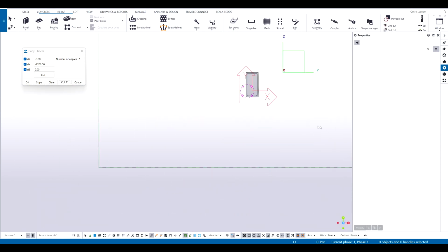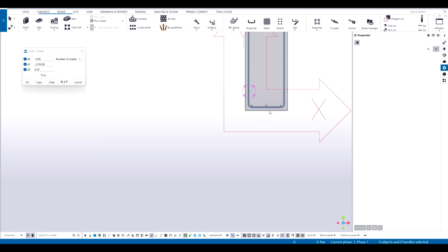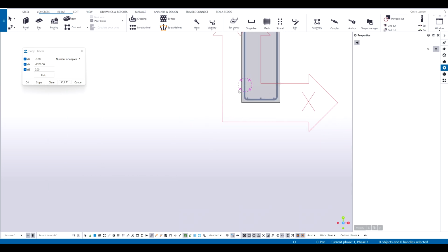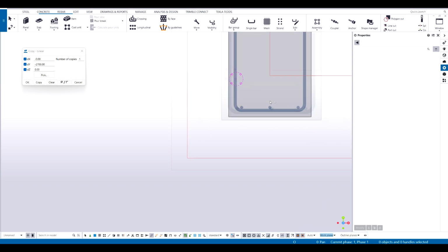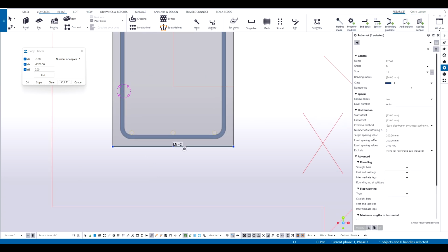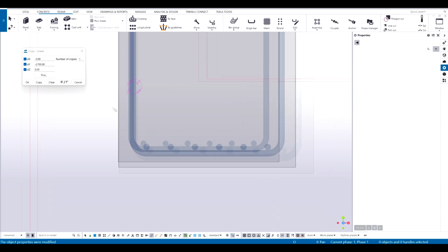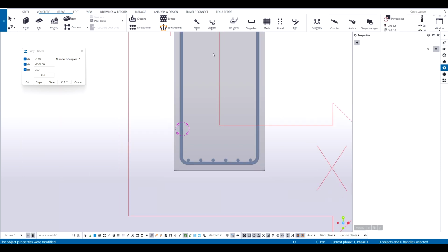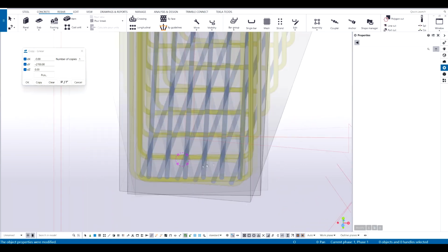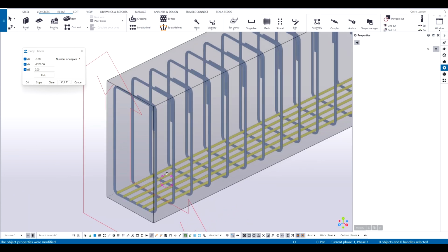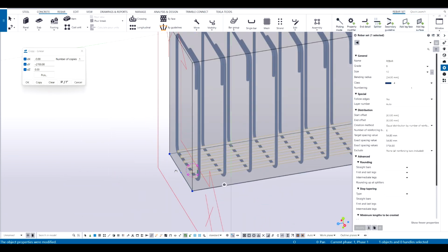I did not create a view or anything, but just set the work plane tool to the view that I wanted, and then I set this up so that I can see this thing. Now my design is having 4 bars, or let's make it 6 bars. Okay, so Tekla has put in 6 bars over here. Now the design may not make sense, but I'm making it like this because I want to demonstrate a few things here.